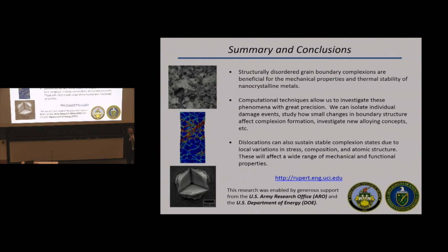So luckily, experimentally, I can never get to that point. I can't quench in thick enough films. And in fact, this is exactly analogous to what people did in the metallic glass community. The way that they toughened these materials was they nucleated out crystallites that formed dendrites and blocked shear bands from going all the way through the sample. So it's actually quite similar, but you have to stay near a side where you have a majority phase, either nanocrystalline or amorphous. Yep. But conceptually, you would converge at some point. Yep.